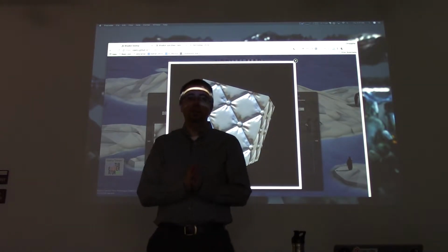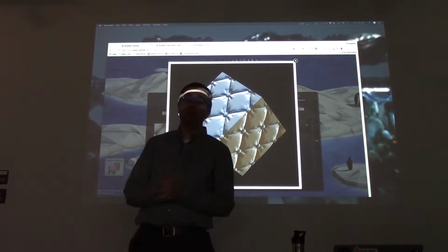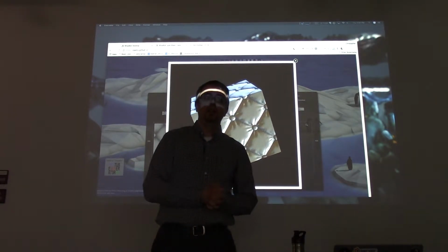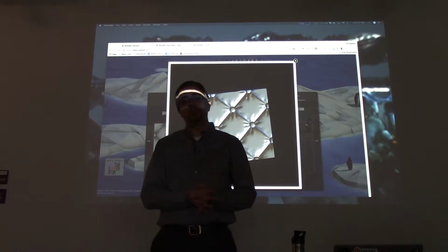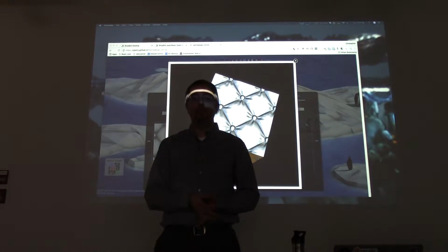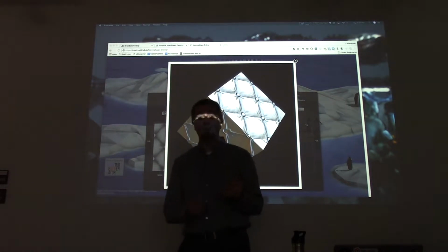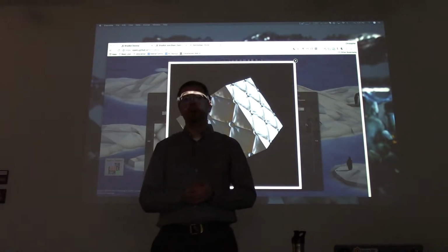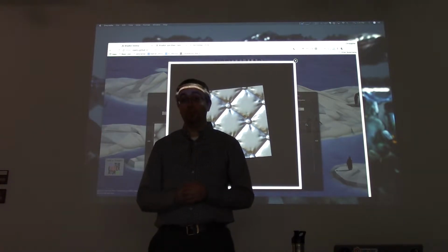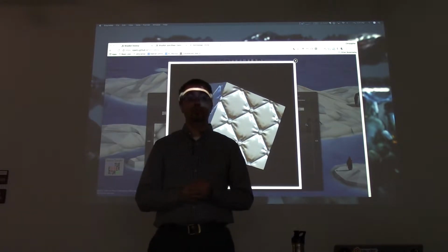Once we are done creating this block, and milling that is going to take some time, you're going to have to do two passes: a rough pass, and then a fine pass. I'll talk about some of that process as we get closer. But once you have that pass, that wood block becomes a positive, and you're going to pull four copies with the vacuum form machine.